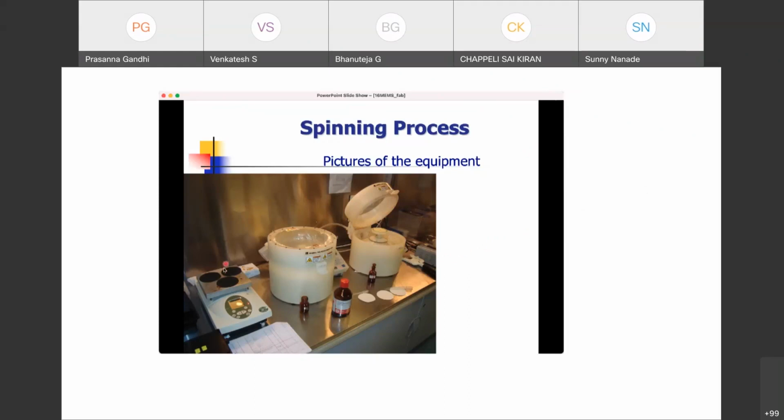So what I was talking about is that even for a simple process like lithography, a lot of other steps are followed before. The wafer is cleaned by a process called RCA cleaning. Then you do a small deposition or spin coating of this photoresist.